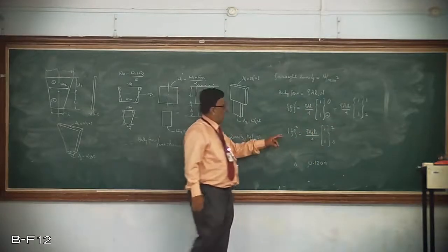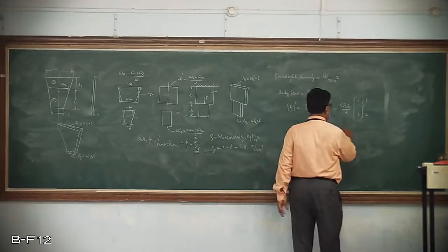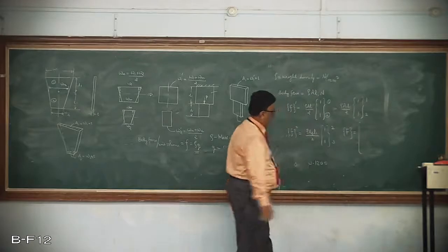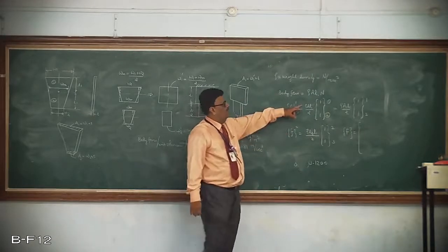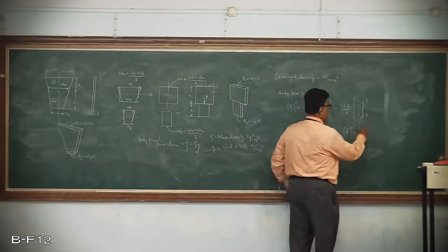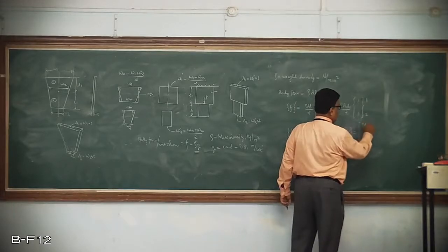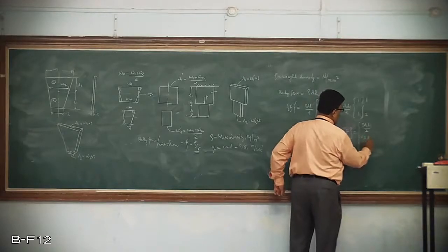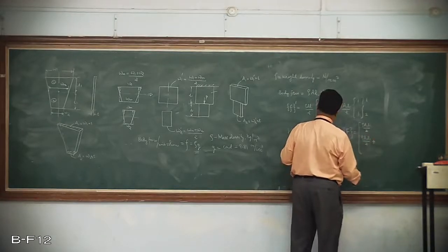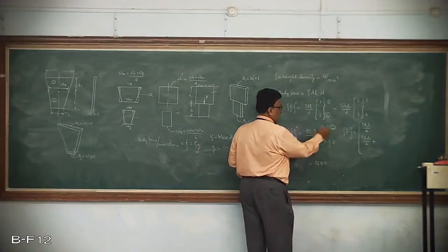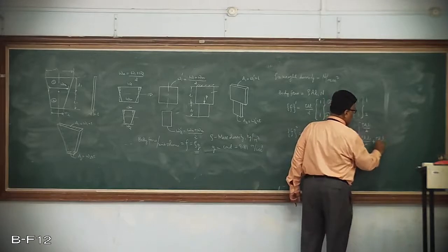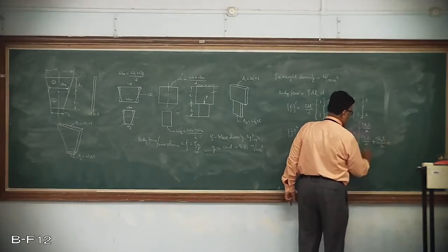Now, using all these, if I want to convert to the global load vector, see, at the first node, only rho A1 L1 by 2 is there. Similarly, at the second node also I have this, but in addition there is a contribution of this, which is also added there. Therefore, I need to add rho A2 L1 upon 2 also. Here again rho A2 L1 upon 2 is going to be there.